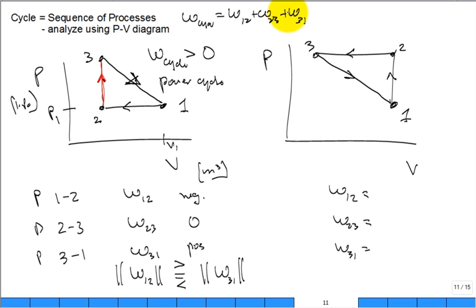And if you have a positive so many kilojoules, you say, oh, for every operation of the cycle, I get that many kilojoules of work out, if it's positive. But take a look at this one. What's the difference? This one's rotating in the general clockwise direction, meaning expanding at high pressures, compressing at low pressures.